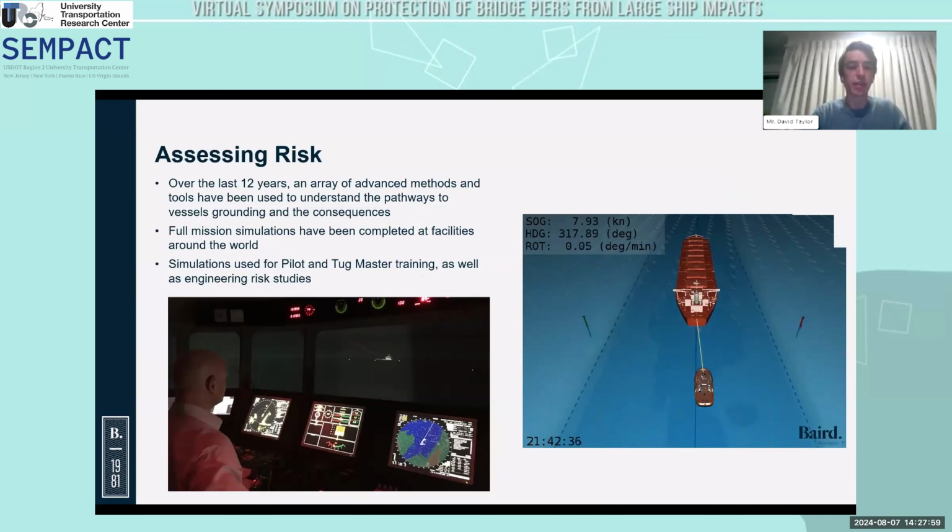Just to give some context, the channel is very narrow. It's approximately 180 meters wide, and these are 330 meter LOA vessels. So the time from a ship going off course to a ship grounding is somewhere on the order of 60 to 120 seconds. You've got 1 to 2 minutes where a ship can be on its intended track, and then 60 seconds later, it can be hard grounded on the edge of the channel.